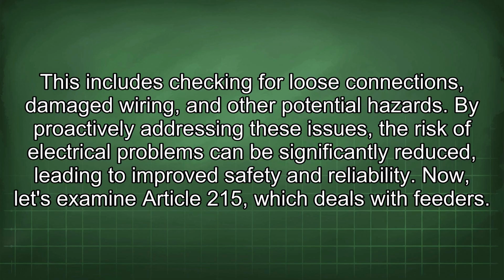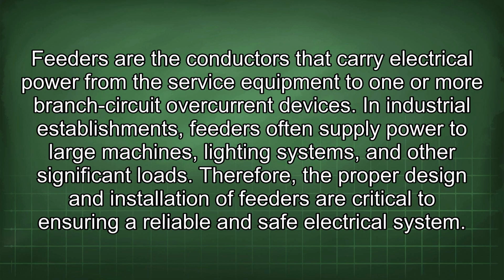Now, let's examine Article 215, which deals with feeders. Feeders are the conductors that carry electrical power from the service equipment to one or more branch circuit overcurrent devices. In industrial establishments, feeders often supply power to large machines, lighting systems, and other significant loads. Therefore, the proper design and installation of feeders are critical to ensuring a reliable and safe electrical system.